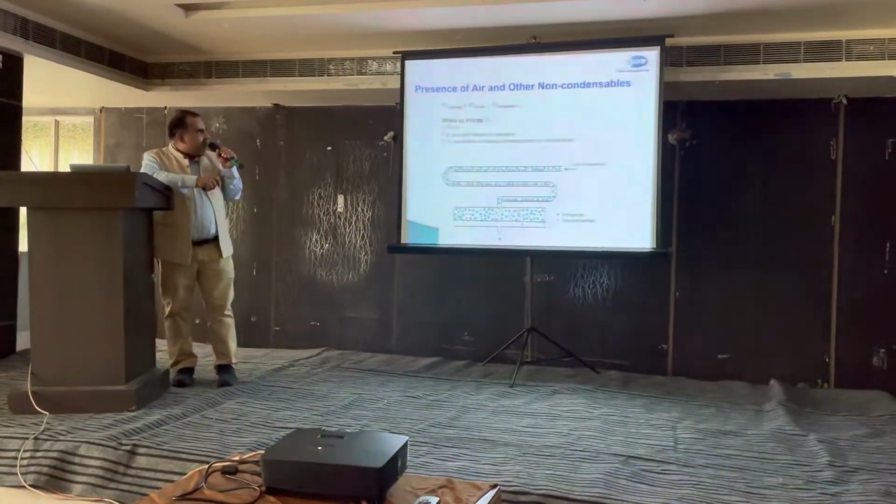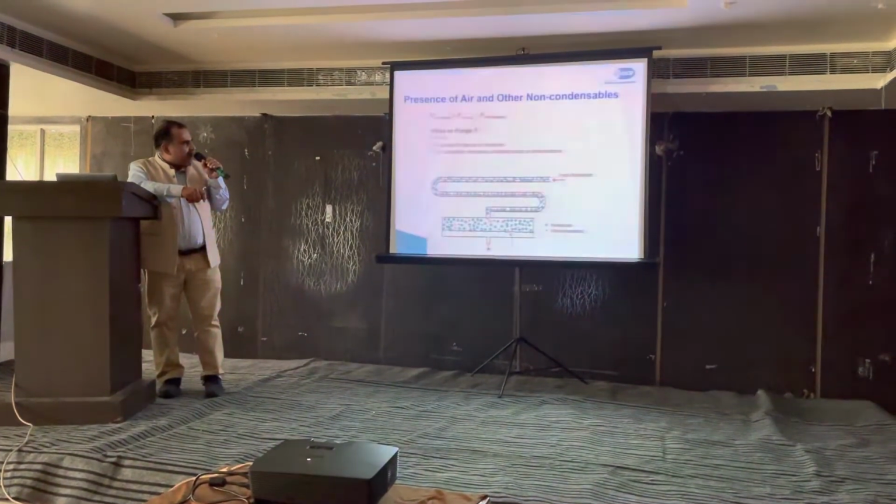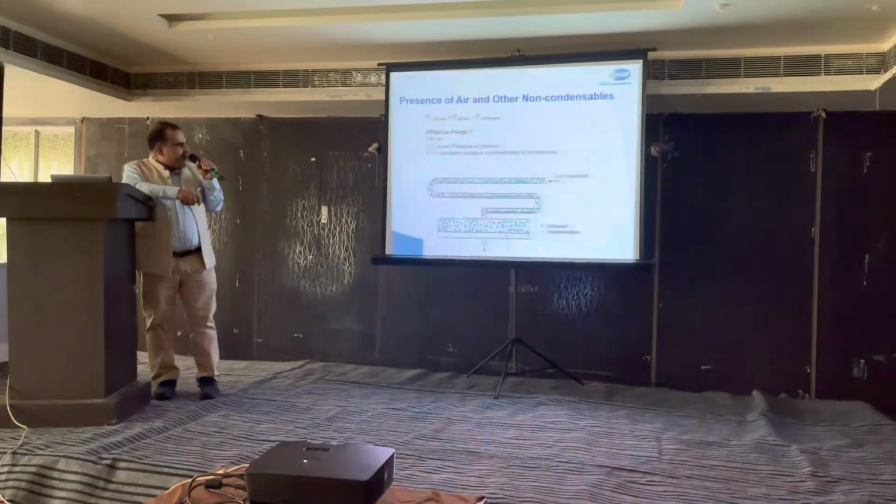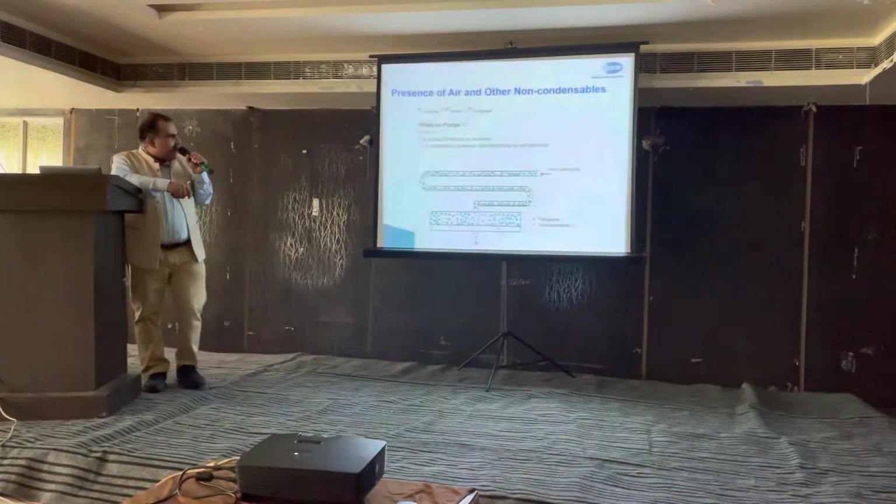So how can you check that? Normally, compressor gas and air both enter the condenser. The ammonia will become liquid and the air will remain as air only.